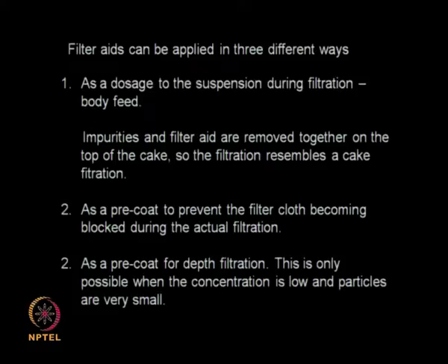If you are doing depth filtration, you can again use it as a pre-coat. This can be done if the concentration is low and the particle sizes are very small, because if the particle sizes are very large in depth filtration, the filter aid will not reach the bottom of the filtration unit.